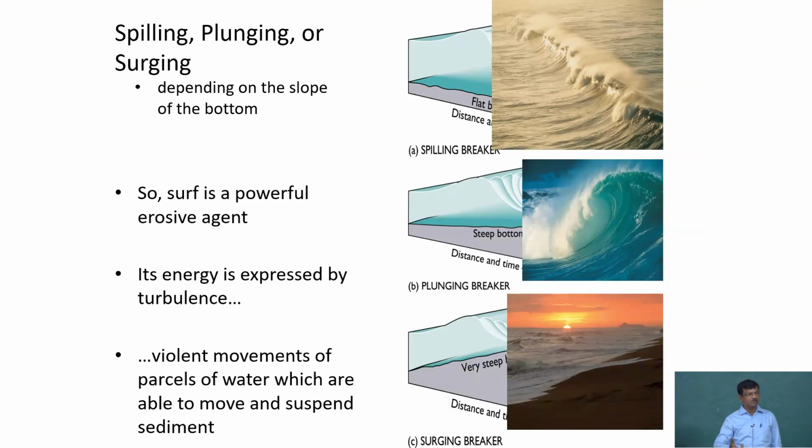It lifts off all the sediment material, then the current induced by both wave and, added upon with, tide will drift the sediments lifted by the plunging wave to the next location. If it is not supplemented from another direction, then there will always be a depriving course to the particular area where the wave is breaking.